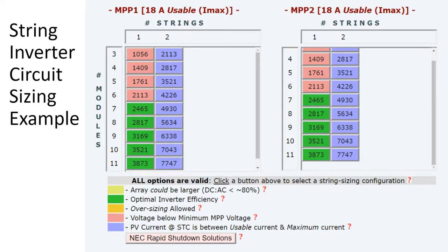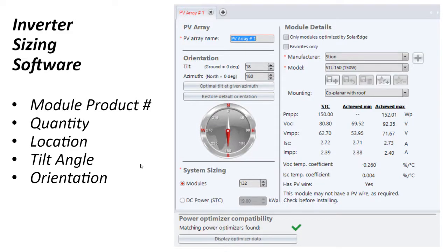Within a single maximum power point tracker, whether it be a circuit or one solar module, all the cells have to face the same direction. So say a pallet of solar has 25 panels. This string inverter could accommodate 2 circuits of 8 solar panels facing southeast on one power point tracker and 1 circuit of 9 solar panels facing southwest, for a total of 25 panel system working on one single string inverter with 2 maximum power point tracker circuits.